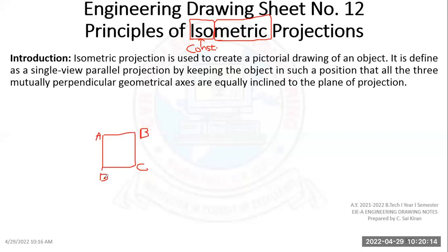So that's the reason, if I'm considering a cube, then I need to make it at an angle. Okay. So this is the angle. If I'm looking at this angle, I have different points, and then I have to give the hidden lines. So there will be hidden lines here. Okay. So these are the hidden lines that you can see. Already you have drawn A, B, C, D. Then this one will be E. Then this is F. This will be G. And this is H.